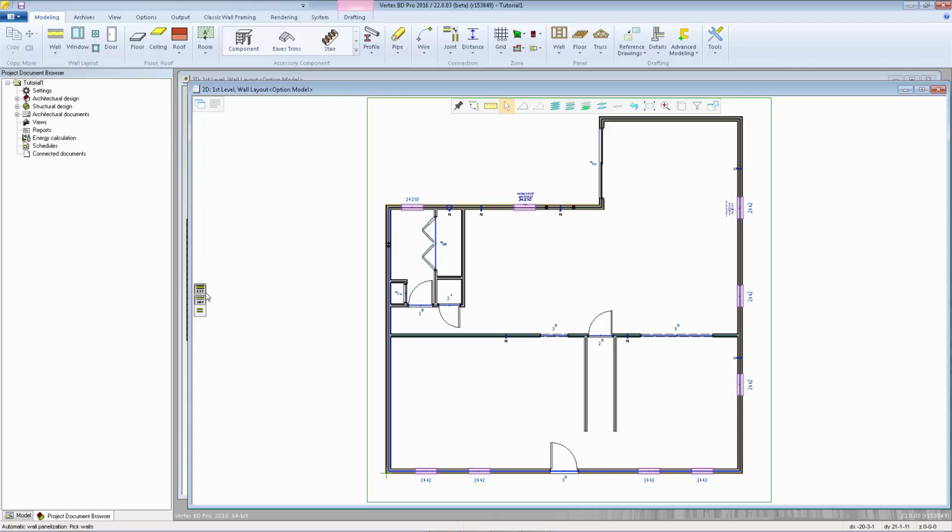We can control if we're going to use the exterior walls, interior walls, or selected walls of the same type. I'm just going to keep both of those filters active and hit Control A to select all the walls, then hit Confirm, and now I can hit Escape.